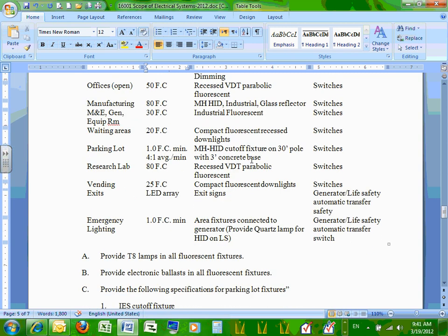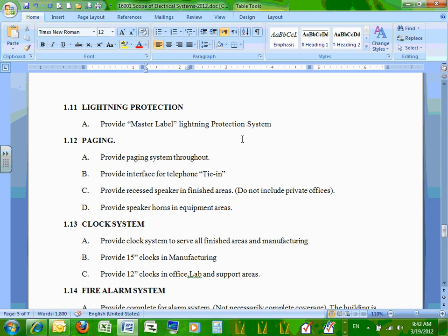So the high voltage controls? They're all high voltage controls or occupancy sensors. When you see an occupancy sensor, guys, it's just an occupancy sensor that drives a relay above the ceiling. You bring the power to the relay and to the occupancy sensor. It's a local control. There's no control panel. Can I get you guys to give a thumbs up, no lighting control panel? Because I'm sure you're looking at the fixtures running at 277 volt. They're not 120 fixtures, they're at 277 volt.